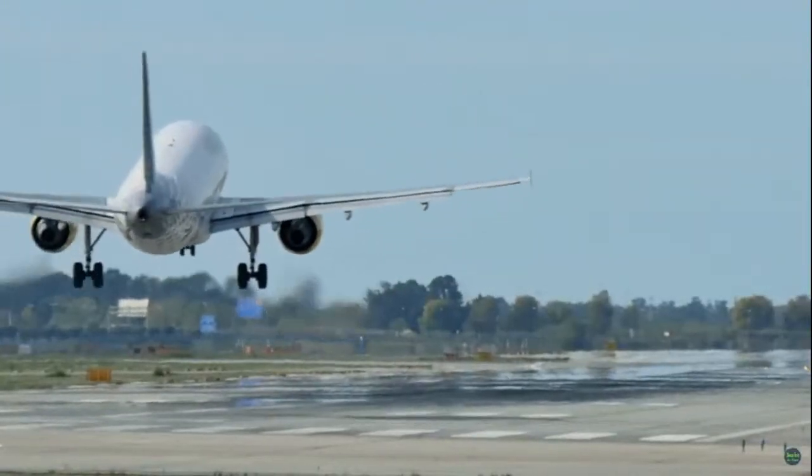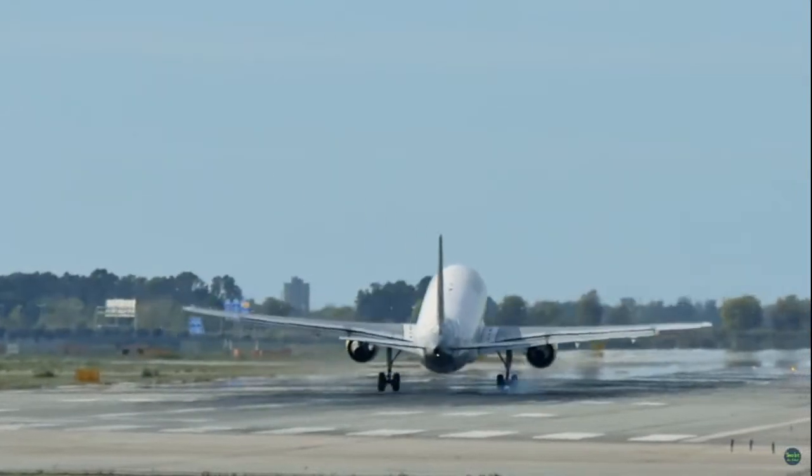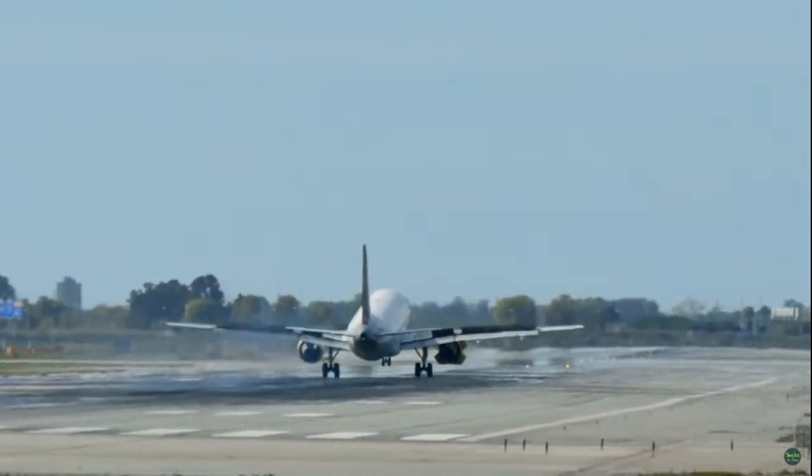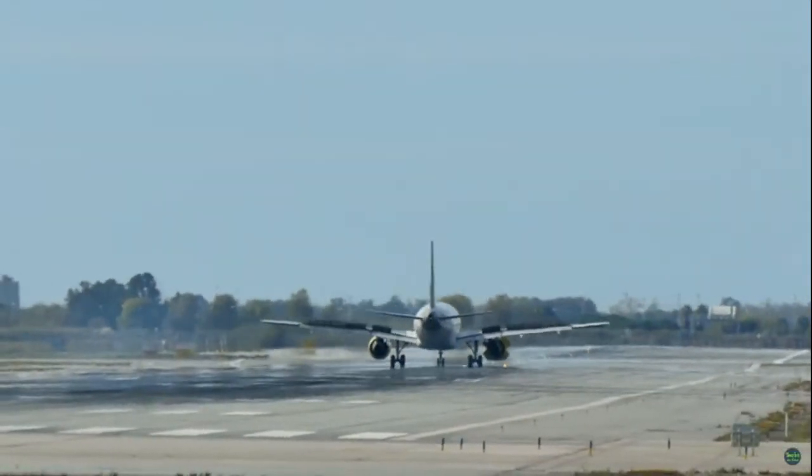Now, this happens because of a phenomenon called ground effect. Ground effect is when an aircraft is flying close to the ground, the vortices coming off the wings are actually hitting the ground and lifting the plane back up. You probably all felt this before when you're coming in for landing. It feels like you should be touching down any second, and there's a few more seconds while you're riding on a cushion of air, plus the pilot is flaring the wheels to make sure there's a nice smooth landing on the main landing gear to minimize damage and to have a nice soft landing.